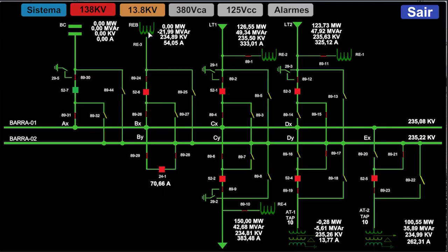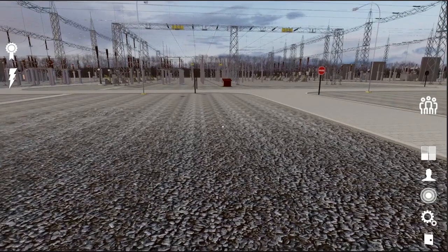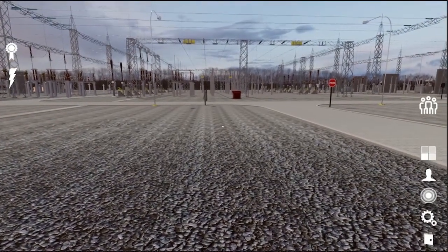Bus reactor. If I open the bus reactor circuit breaker, I'm going to raise the voltage. So the voltage goes up. If I close the capacitor bank, the voltage will go up even more. It went up to 200. All of this is calculated, folks. So I can do, for example, a simulation where I open the capacitor bank, if I'm not mistaken, the first one.